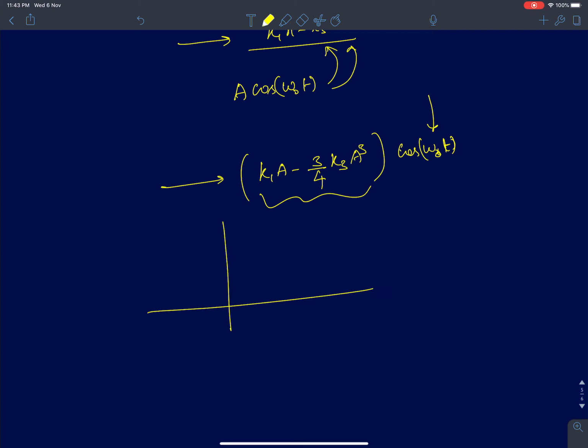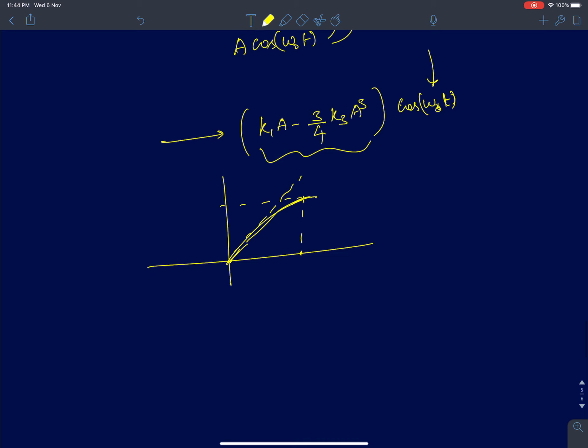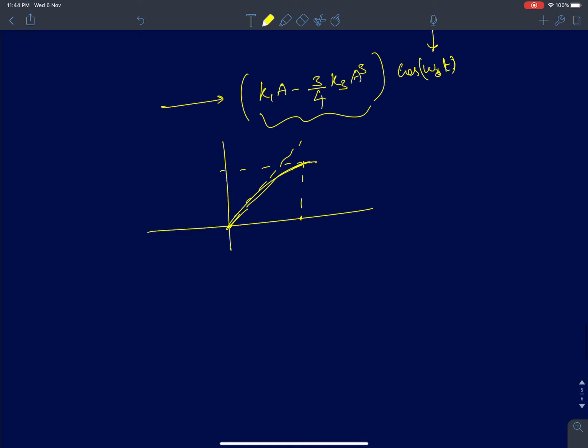We said that to tell us how nonlinear the system is, we will characterize the amplifier. If I want to compare multiple nonlinear amplifiers, this is one good metric. It tells you how nonlinear the system is. We said it is the point where the gain reduces by 1 dB from its nominal value. And I told you that corresponds to approximately a 10 or 11% reduction, 11% to be precise, in the actual gain.